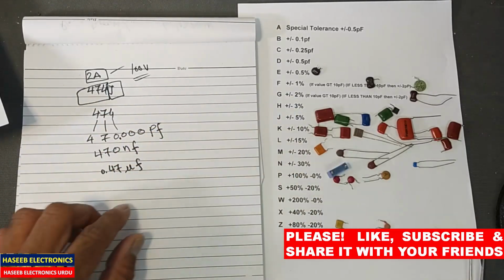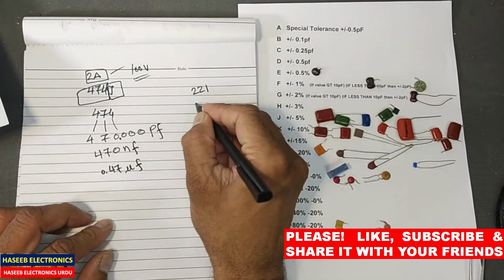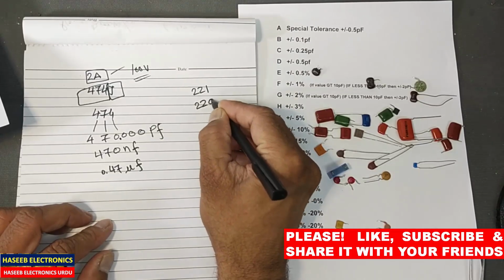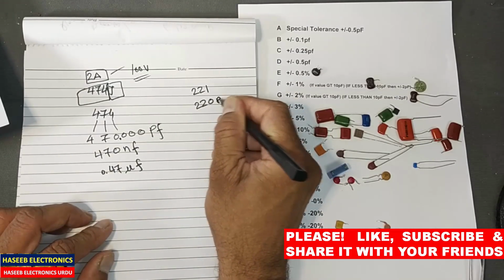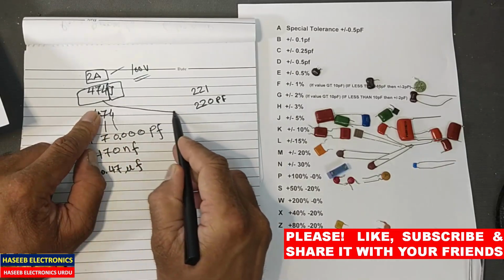If it is 221, that means 2, 2 and 1 zero, 220 picofarad. You can decode the capacitance in this format.